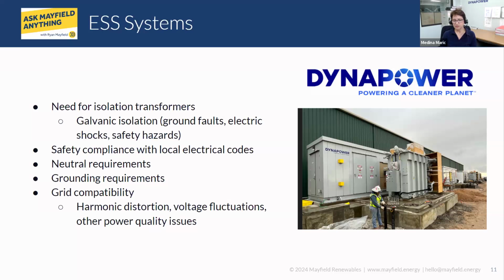Noise reduction is also the same. PV systems will sometimes, especially PV systems, create a noise or be very sensitive to that noise if it's coming from the input side, and that gets suppressed and filtered through transformers. I'll grant you that there is a lot of noise and those transients that will go through the transformer, but it's much easier to capture them on the secondary sides, and there are also ways of capturing those transients and suppressing them so they don't transfer on the PV equipment and equipment that is behind the transformer, looking from actually the user point of view, not the grid point of view.